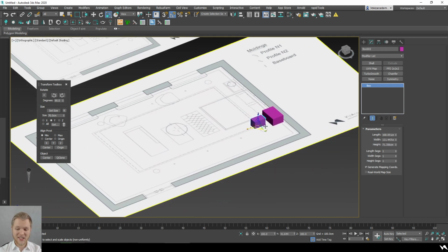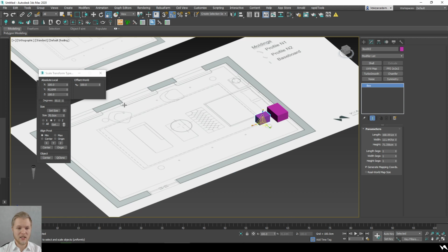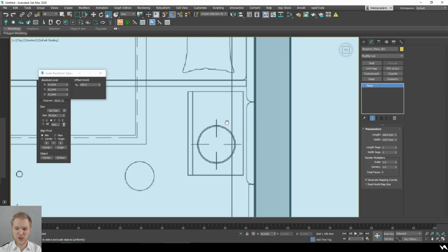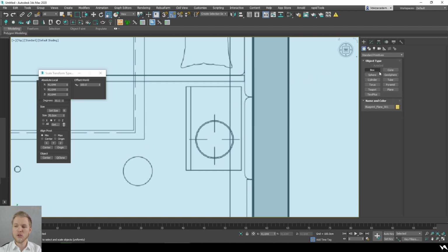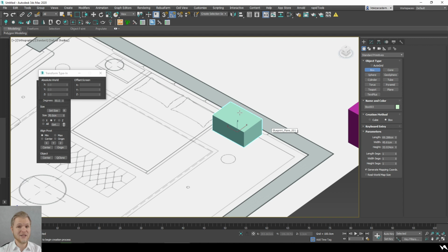So since we already scaled this, I'm going to copy this scale from the Y axis and use it for this whole object. By the way, guys, remember that you will be able to re-watch this webinar later on. So let's copy this scale from the Y axis to our main floor plan that we're going to use, type it in the world coordinates, and just press enter. Now, when we create a box, just following this object, you will notice that this image is now in proper scale. So we're actually creating something that is 70 centimeters wide, and that's a very good thing.